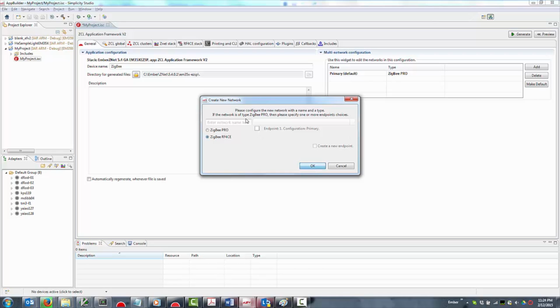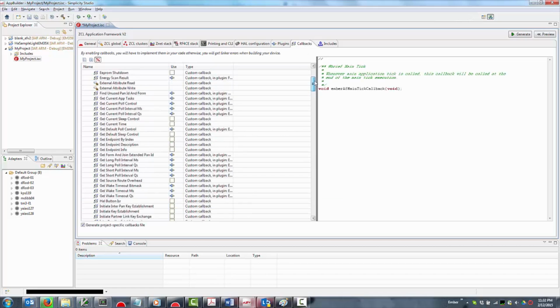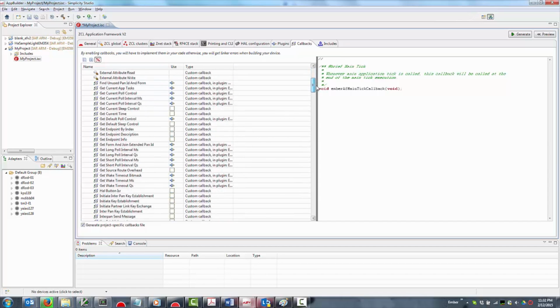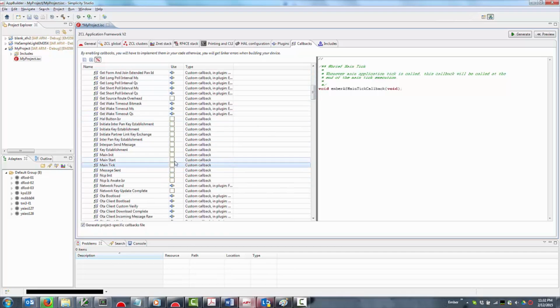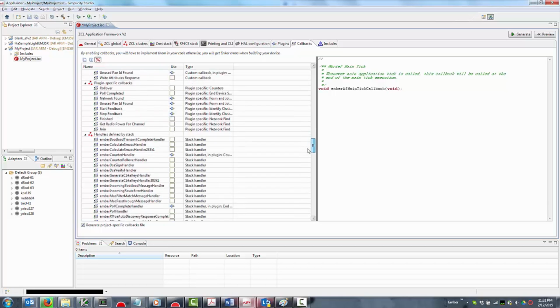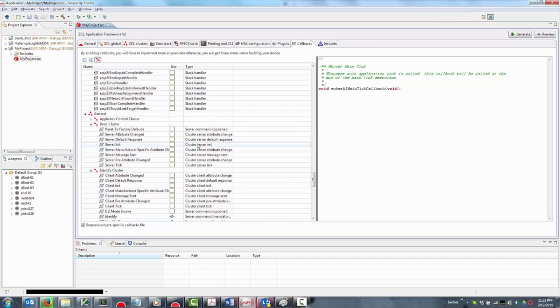One of the things that makes AppBuilder so versatile as a starting point for applications is its callback interface, which allows user applications to be notified about important events or make decisions based on runtime state. Software designers can choose which callbacks appear in the user's callback C file, and the rest are safely defined as empty stubs within the framework until they are enabled. Callbacks are the places where custom application code can be added on top of Silicon Labs' existing framework to give that application unique behaviors and decide how it'll react.